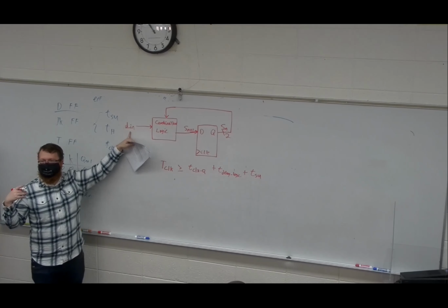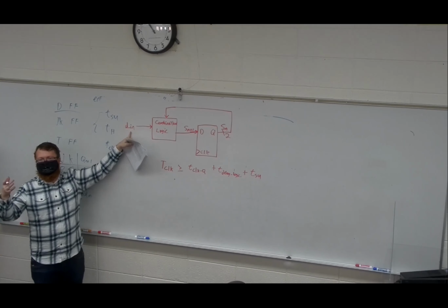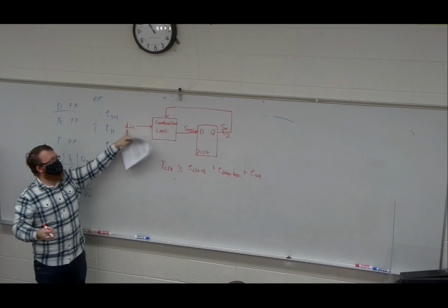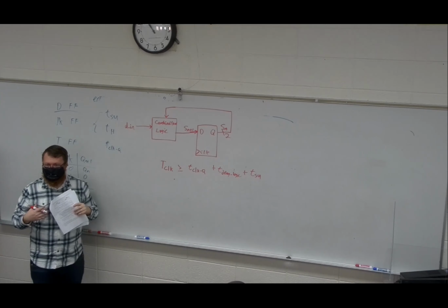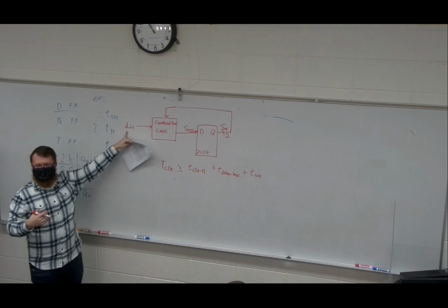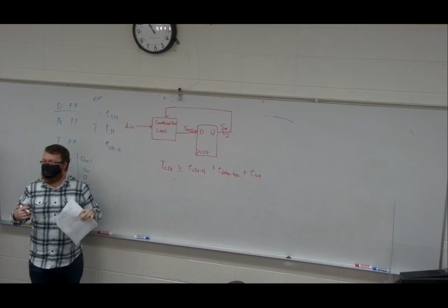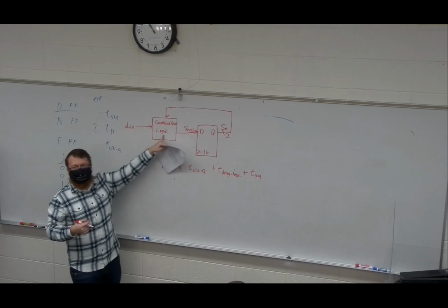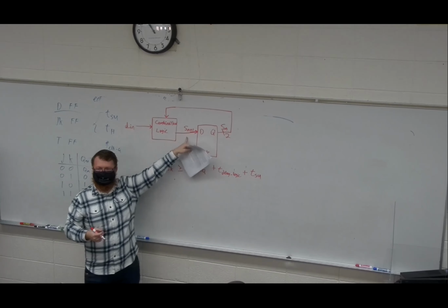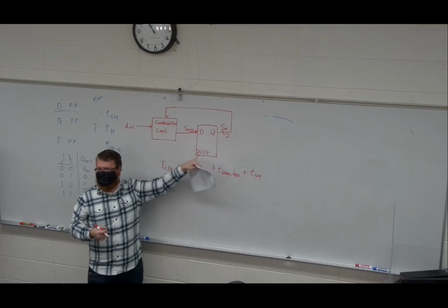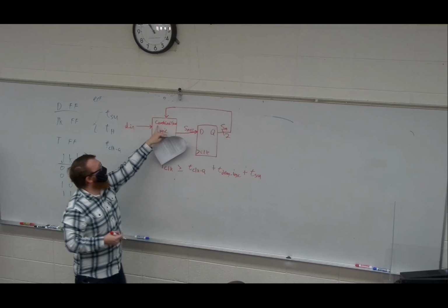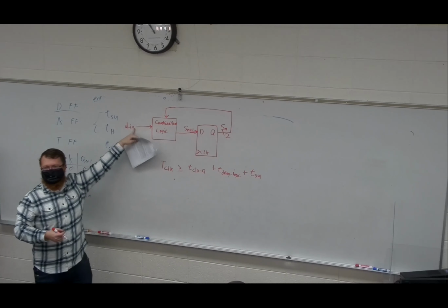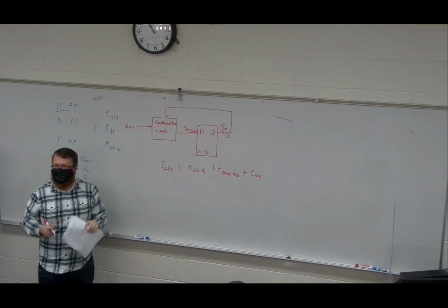Well, we could have something like a light sensor. So it's nighttime, a car pulls up, it detects light, this asserts 1, and says, oh, if I am red and there's a light sensor on, I surely need to transition to green. So the combinational output is going to say your next state should be green. The clock hits, green gets put out, goes back to this combinational logic and waits for the inputs to tell it when to leave that green state.